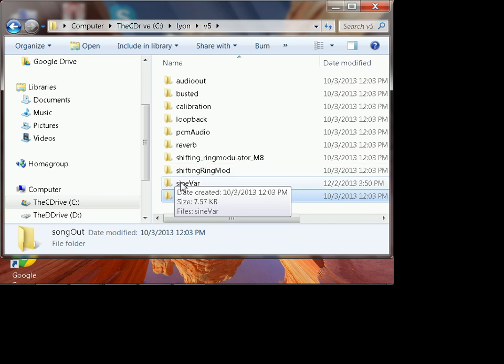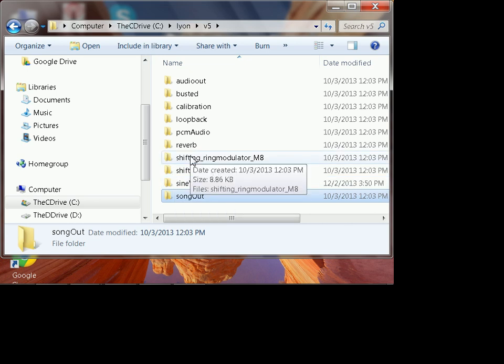So I've got a few other things in here which are really targeting what I would call audio processing. But in order to do audio processing with an ADC on a microcontroller, you have to give the ADC something to bite on. The ADC in this microcontroller wants to see a signal that varies between 0 and 5 volts. Does anybody know the amplitude of a microphone signal? It's not 0 to 5 volts. It's more like 0 to 10 millivolts.